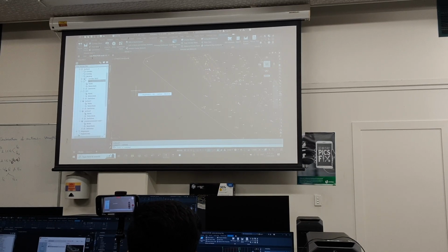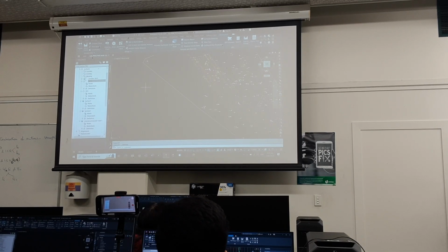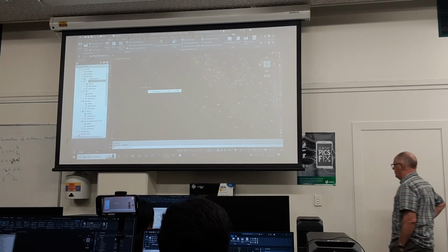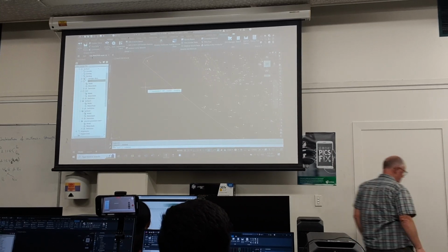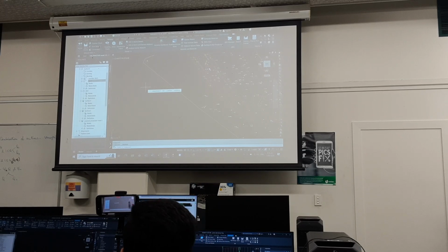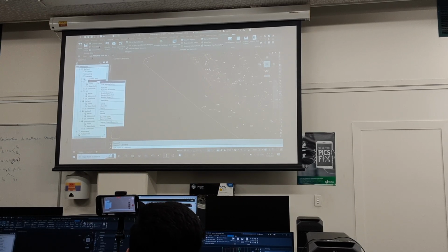In order to do that, we're going to right-click on the contours, on the EG1 again. In my case, it's EG space 1. And we go to the same edit surface styles. You have to make a change in your contour interval to 0.2 and 1 metre.